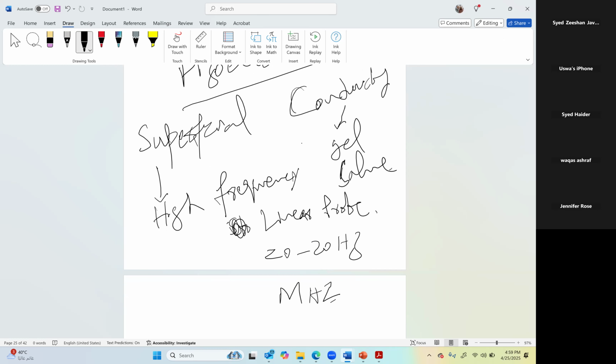So these high frequency sound waves pass through the piezoelectric crystals. They are vibrating, then they are reflected by the structures which we are scanning, and there is a conducting material. Then the reflection comes back again. Piezoelectric crystals are vibrated, and the reflection will be according to the structure from which it is reflected. That is taken by the probe, converted into an electrical signal and shown on the screen. This is the basic principle. I don't know too many details, and nobody actually expects you to tell too many details. This one is enough.